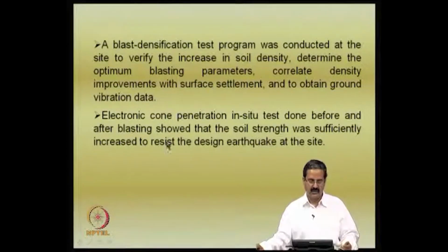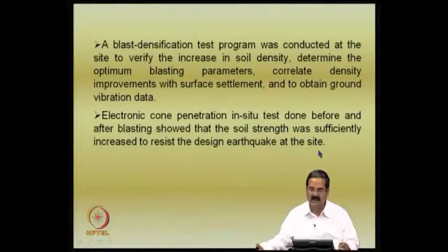They did cone penetration tests, in this case electronic cone tests before and after, and the results showed that the soil strength had improved and increased to resist the design earthquake at the site. What was required was a very good ground improvement technique to match the design earthquake force.